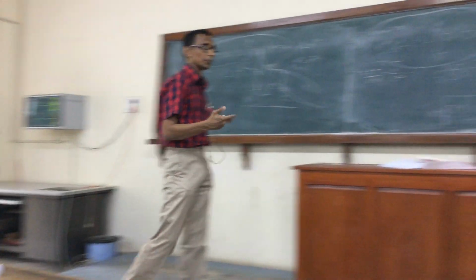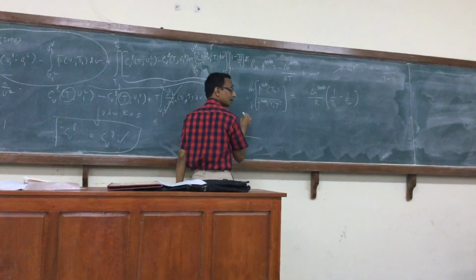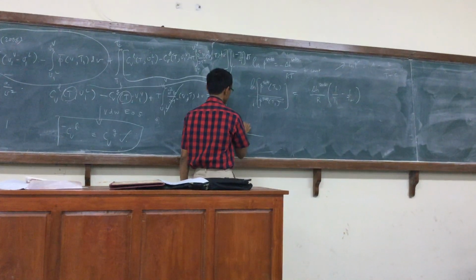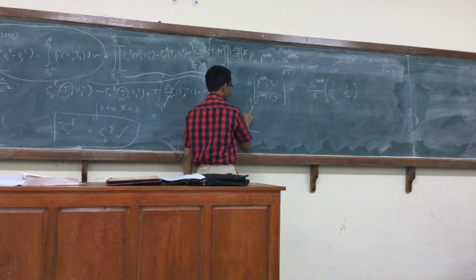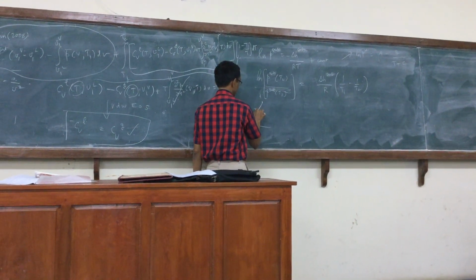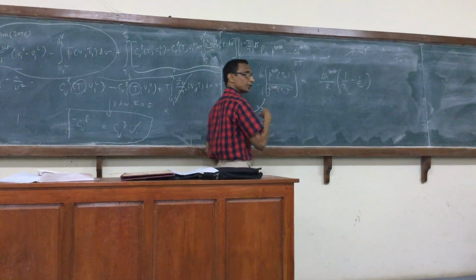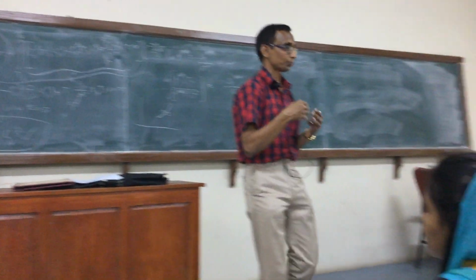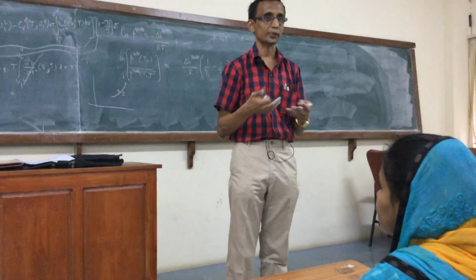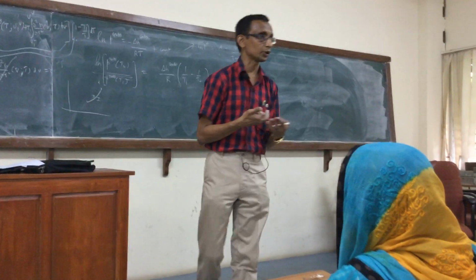So that problem with Maxwell's rule is overcome by choosing this. This is also important because we also see the role of the critical point even practically. Right? And practically, if you want to reach from one state to another, let's say I have state 1 and state 2, liquid to vapor, without having to deal with the phase transition. Because practically, when you have to deal with two phases, processing and all that will be more difficult. Handle two phases.